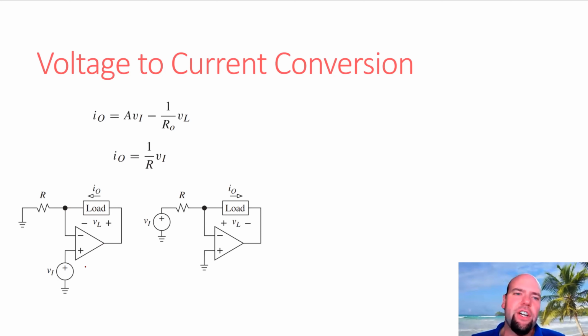What about voltage to current conversion? Well, when would you want to convert a voltage to a current? Well, one of the things is currents exist a lot in the natural world. Currents don't generally play that nice with voltage control devices like CMOS-based electronics. Generally they prefer voltages as input-output signals to currents.